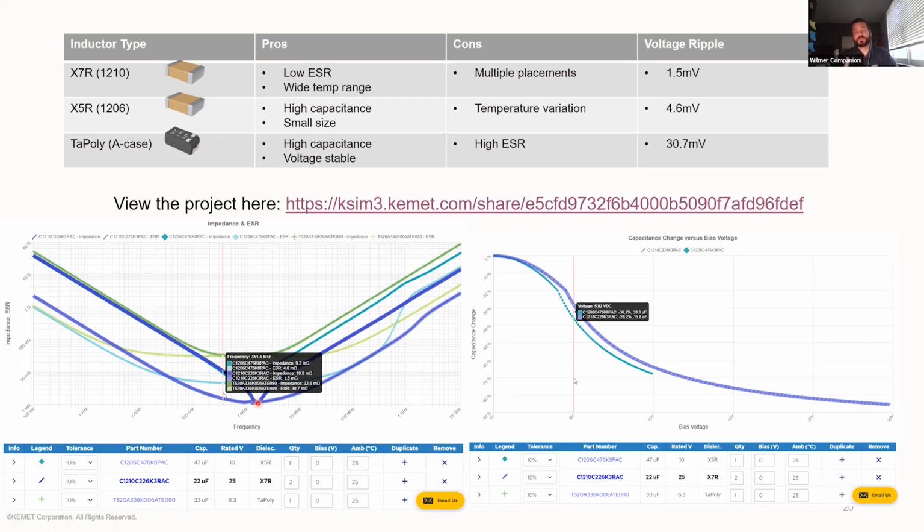So these specific mounting options do have an impact on temperature rise. We actually also have some of our stacking technologies that you can place ceramic capacitors not in the sort of pancake stacked orientation you would think of. You can actually mount them on their side where each individual capacitor is perpendicular to the board. And that also has an impact on how much heat is dissipated. It makes for a better radiator that way.